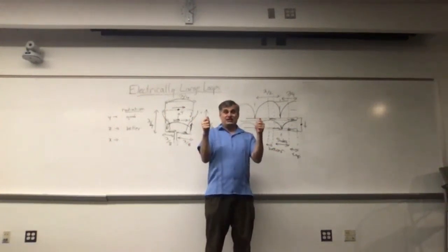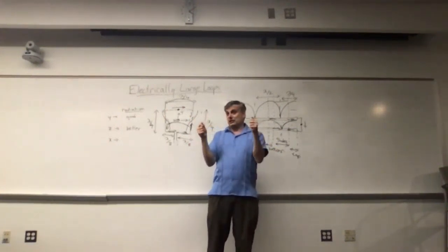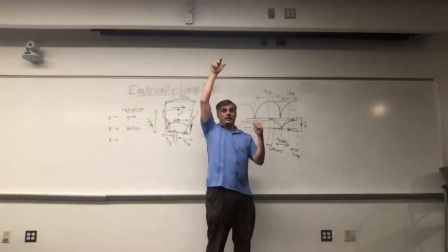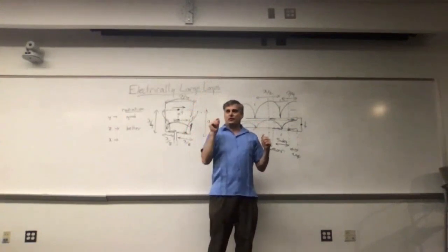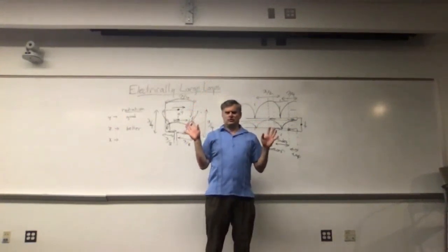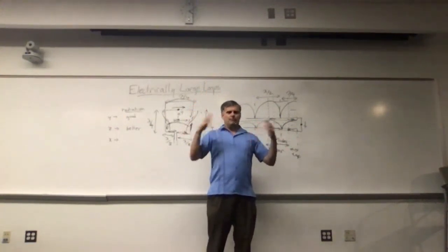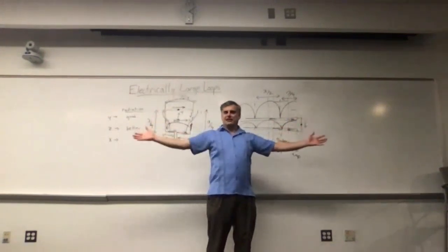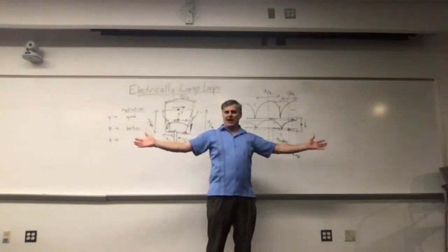If you take this deep null and you tilt the antenna just a little bit to the left or a little bit to the right, the source will pop up again. So it gives you a technique for doing direction finding with what is typically considered to be an electrically small and kind of fat-lobed antenna with very little half-power beamwidth.